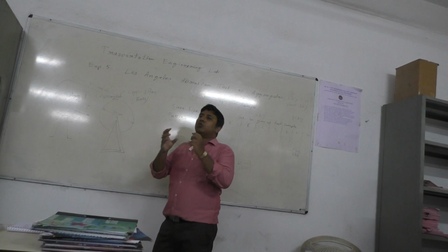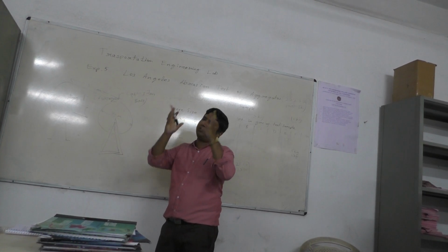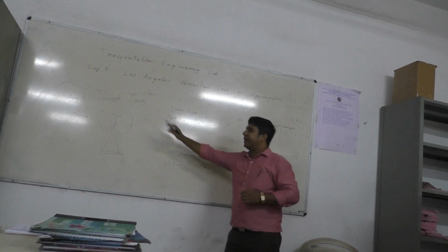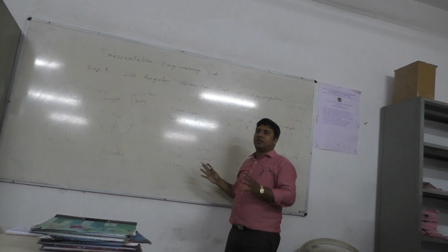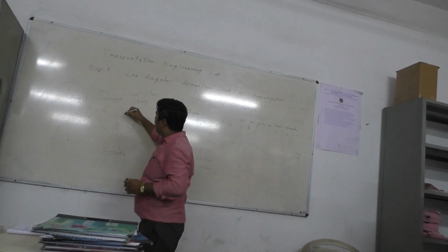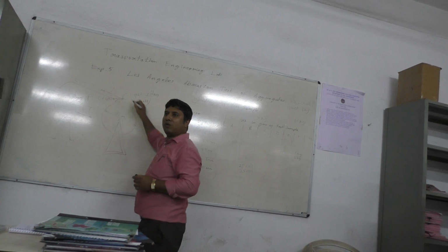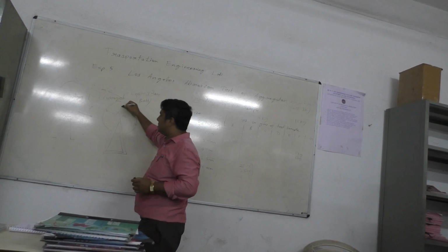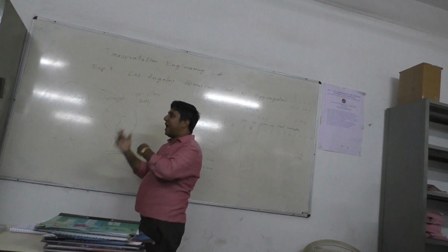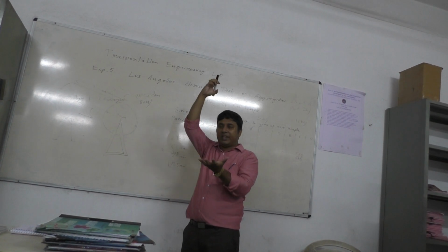After removing, the samples will not be the same as they were previously. After rotation, this size won't be there. When it rotates, the steel balls will fall freely over the aggregate. While rotating, these steel balls act as the abrasive charge, and as they fall they give impact.